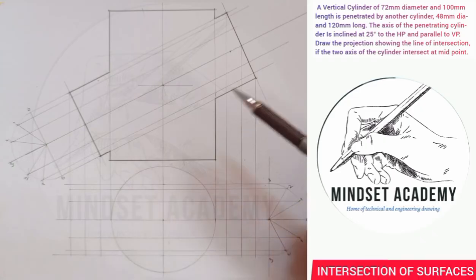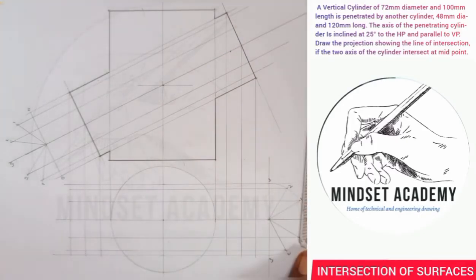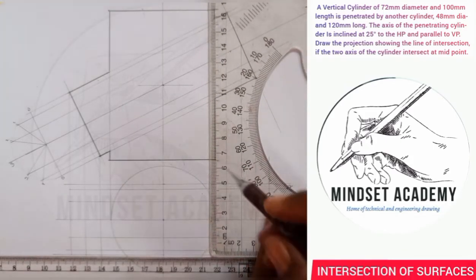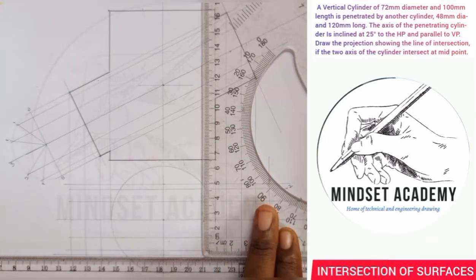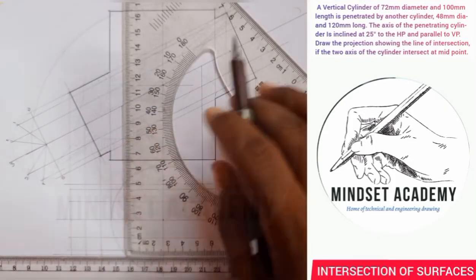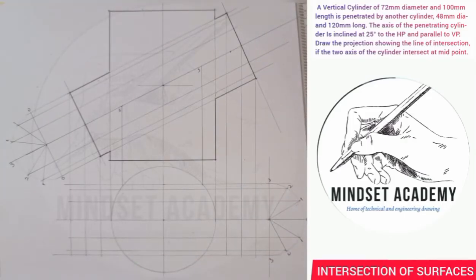After we've done that, the next thing we are going to do is, where this line intersects with the circumference of the circle, we start projecting them up. So let's start doing that. If I project the line of 3, this is where the line of 3 meets here, placing it on my T-square. Just put it this way. So where the line of 3 meets, at this point. Can you see? And this is also 3 here, meeting at this point. This is our line of 3 here. So I'll just call it 3. And this is also 3.